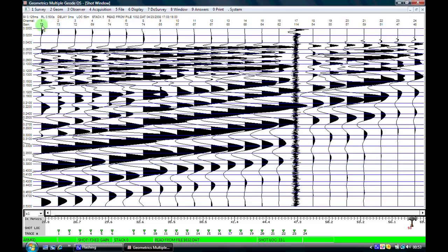You'll note initially that the numbers here on the left hand side of the screen are in the 70s and the 60s, etc., and as we come across to the right hand side of the screen, get gradually smaller. So the number on channel number 24 is 46, and this designates that we're showing a smaller amount of amplification on these channels. The blue horizontal lines are travel time lines, and along the x-axis on the left hand side of the screen we have the travel time in seconds, from 0 down to 1/2 of a second at the bottom of the screen.